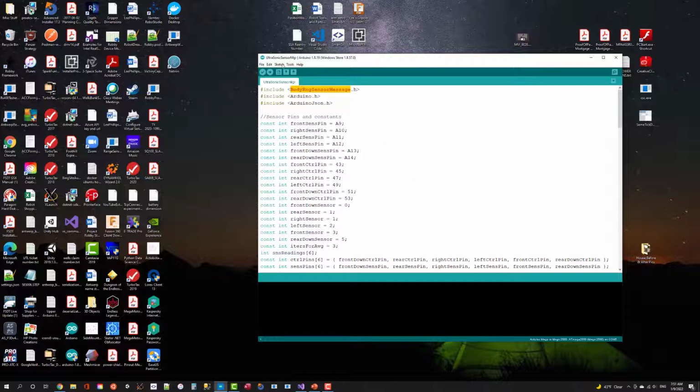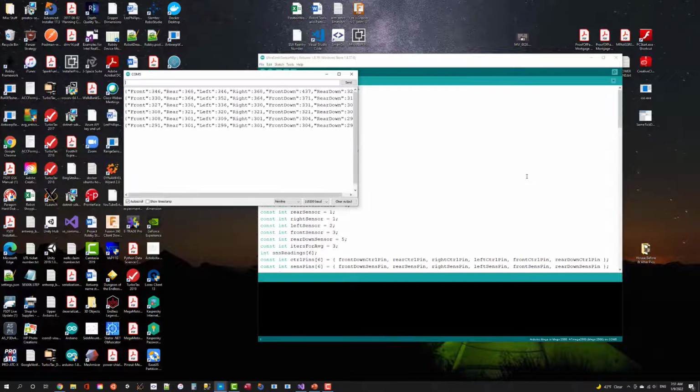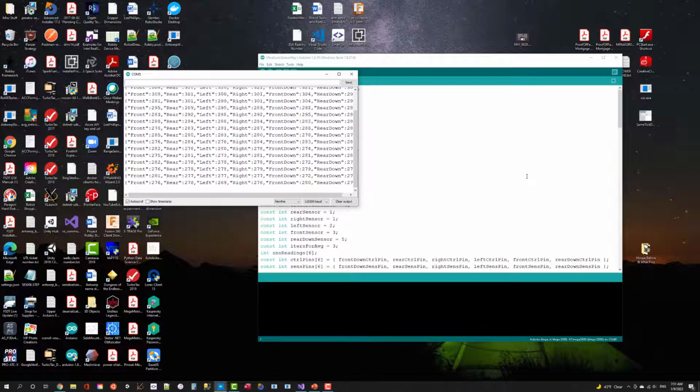Okay, so before we leave here, let me just show you what it is we're looking for. This is the output that's coming out of the Arduino card right now. You can see it's basically just an integer running between the 250s and the 270s that's showing us the current analog voltage on that pin.